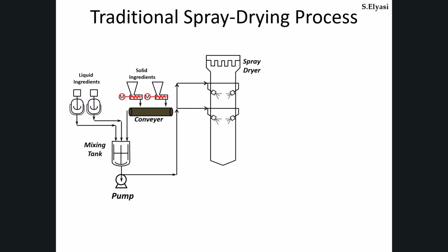Spray drying is widely used in detergents because it is fast, continuous, and can produce powders with controlled particle structure, though it can be energy intensive and may face wall deposition and dust handling challenges. In this process, superheated steam enters near the bottom and flows countercurrently upward. Steam rapidly evaporates water from the droplets. Because drying occurs in seconds, a shell forms quickly and a porous particle develops, helping create the characteristic low-density powder.